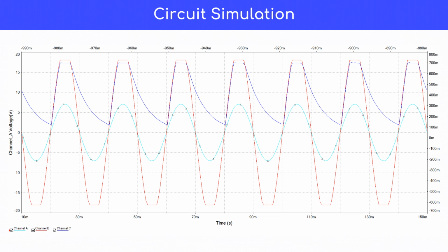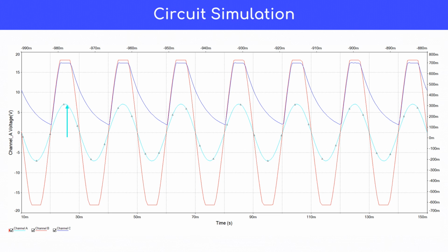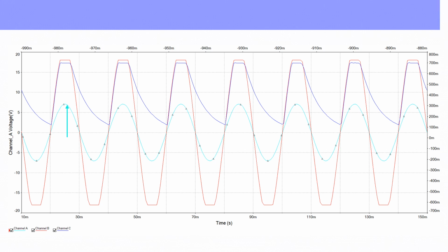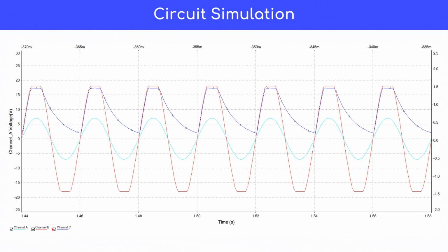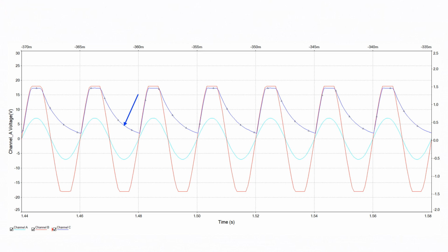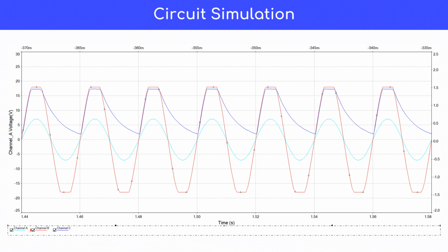This is a graph we obtained from the Multisim program simulator. As we can see, there are 3 different lines in the graph. The turquoise line here indicates the input voltage of 7 V. Upon going through the band pass filter, the voltage is increased to 18 V. On the other hand, the dark blue line indicates that the LED is blinking when there is no object obstructing the ultrasonic sensor. Lastly, the red line represents when the LED turns on completely, indicating there is an obstacle.